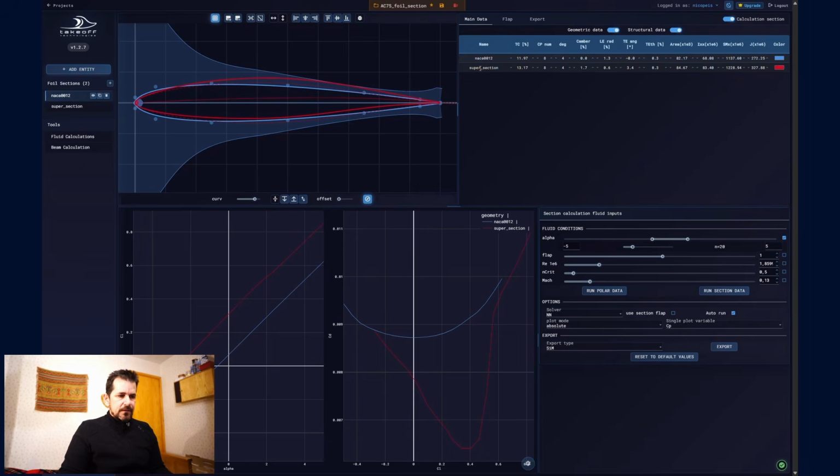The thing is now, normally the America's Cup boats don't change the angle of attack. What they do change is the flap. To be really correct, they change the angle of attack, but mainly when you see them sailing, what the foil trimmer is doing is changing the flap angle a lot. So he controls the right height of the boat with the flap angle, not with the angle of attack of the boat. So normally we're going to consider that the angle of attack remains the same, and we're just going to change the flap angle.